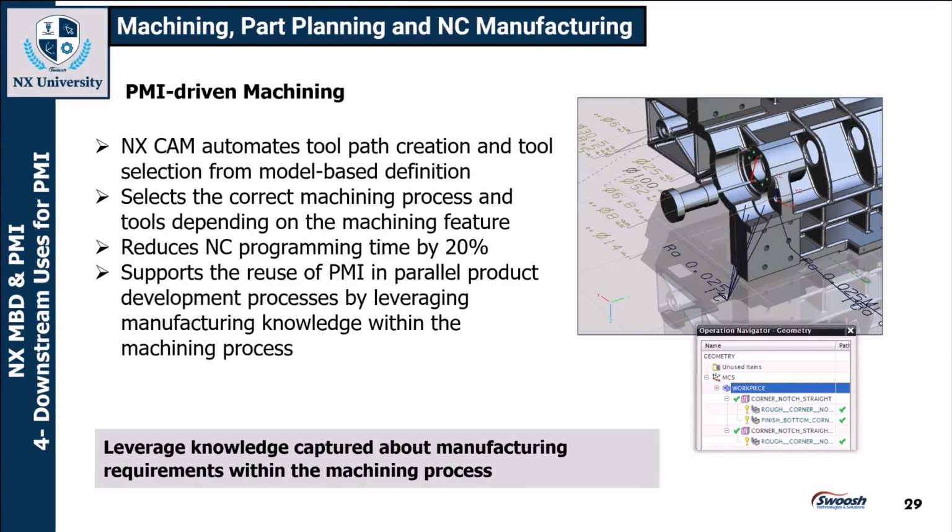Machining, part planning, and NC manufacturing operations, we can use that PMI, and the NX CAM is going to automate your tool path creation and tool selection from the model-based definition information. It's going to select the correct machining process and tools depending on the machining feature, and is going to reduce NC programming time by up to 20% here. So another time savings. It supports the reuse of PMI in parallel product development process, and it leverages manufacturing knowledge within the machining process here. Line item on the bottom there, leverage knowledge captured about manufacturing requirements within the machining process here.